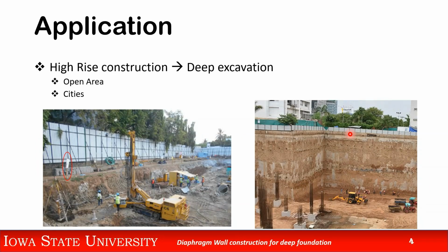Application. Do I need a retaining wall always for deep excavation? No, you don't. Because if you look at the picture here, the first one on the left side, I don't have a retaining wall. This is the main excavation area for the foundations and you do not see a retaining wall. That is because the soil which is experiencing the lateral pressure is the weight of the soil and the groundwater table. It does not have any structures nearby.